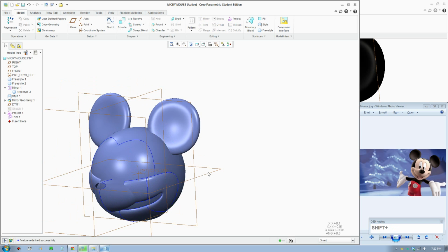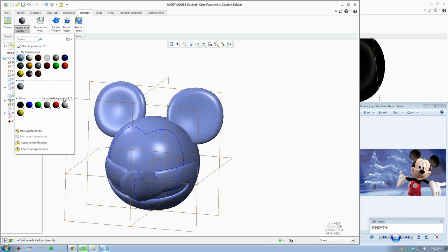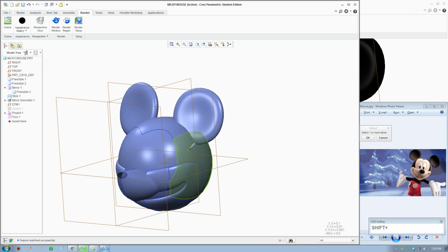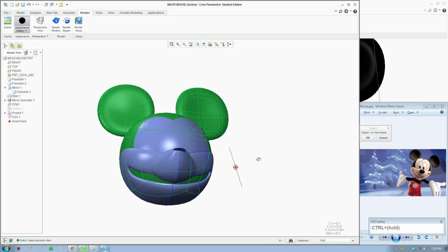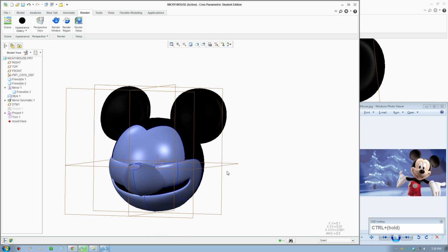So right now I'll go in and add some colors. Go to the rendering tab and switch to, click this button here, go to plastic and glossy plastic. So click the black color, switch to intended surface. Yep, that's good. Click OK here and that'll create that color.